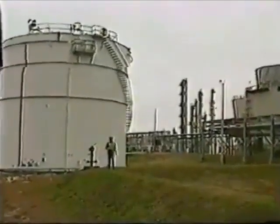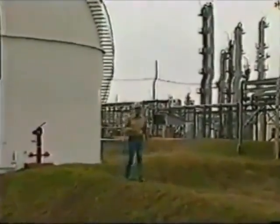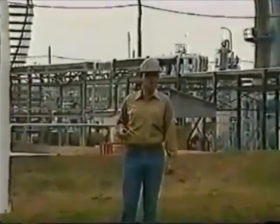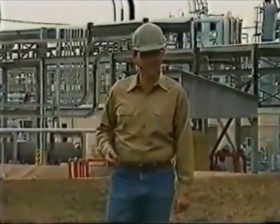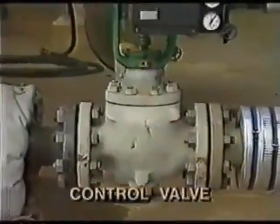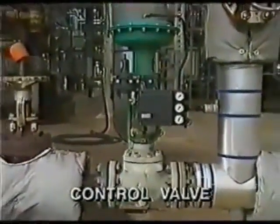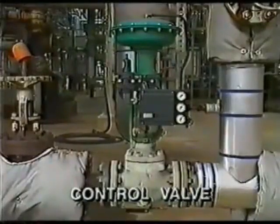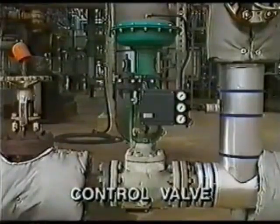So far in this program, we have mainly focused on valves that are operated manually, either by hand or by motor. In any manufacturing or process industry, however, there are applications where it is desirable or necessary for valves to operate automatically. When automatic operation is desired, a control valve is used to regulate the flow of fluids. The body of the control valve can be designed like any of the manually operated valves we discussed earlier in this program. But instead of a hand wheel or a lever, a control valve is equipped with an actuator that moves the valve stem.